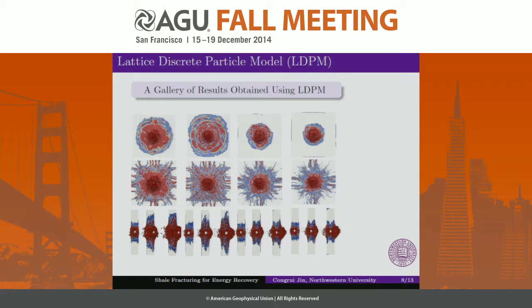This figure shows LDPM simulated damage distribution and crater formation for the simulation of projectile penetration through a concrete slab. LDPM successfully replicates the behavior of concrete for penetration and perforation, and is able to accurately capture the main features of concrete response in terms of projectile deceleration as well as the fracture patterns.